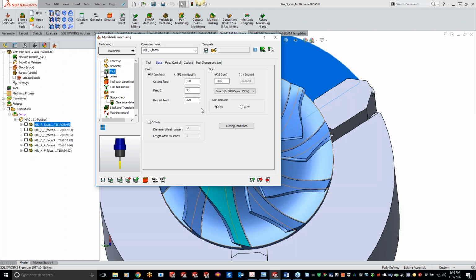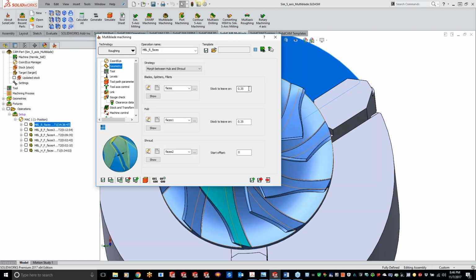So you guys definitely pick feed rates that you are comfortable with. Especially for roughing, we can crank that baby up since we're leaving 0.35 millimeters on the wall and the floor. I don't really have to care too much about a finish, as long as I just don't snap off my end mill. So, yep.